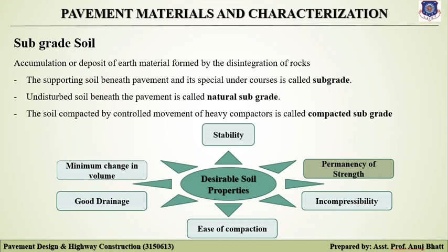If the applied stress on the subgrade is very low compared to its bearing capacity, the deformation due to load would be elastic, or fully recovered when the load is released. This is possible when the applied stress is very low.